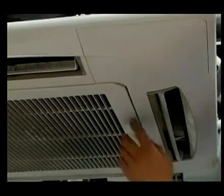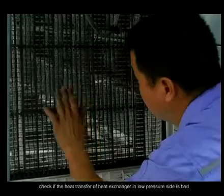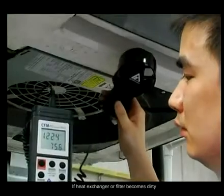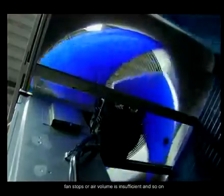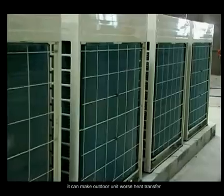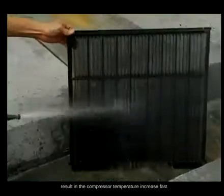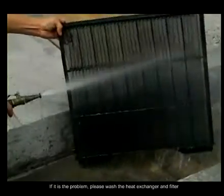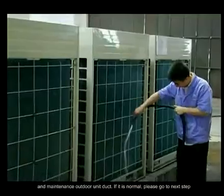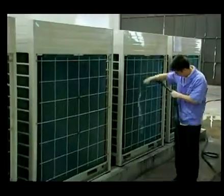Step 3. Check if the heat transfer or heat exchange in the low pressure side is bad. If the heat exchanger or filter becomes dirty, the fan stops, or air volume is insufficient, and so on, it can make the outdoor unit's heat transfer worse, and the working condition is terrible, resulting in the compressor temperature increasing fast. If it is the problem, please wash the heat exchanger and filter, and maintain the outdoor unit duct. If it is normal, please go to the next step.